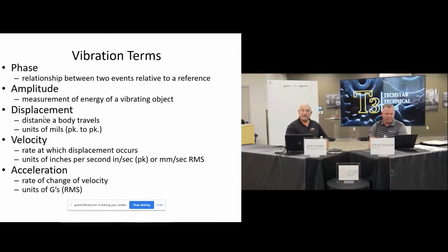There was one question that came up, and you may be addressing this later in your presentation, but it was asking about triaxial monitors that go to your phone, pros and cons. So it mentioned XYZ monitors, but basically a triaxial sensor, the pros and cons of triaxial. Yeah, and probably talking about using some sort of app that will monitor a triaxial. That's what I would say is a cheaper way to be able to monitor. The accuracy is probably within 10%, and you're able to see all X, Y, and Z at the same time.